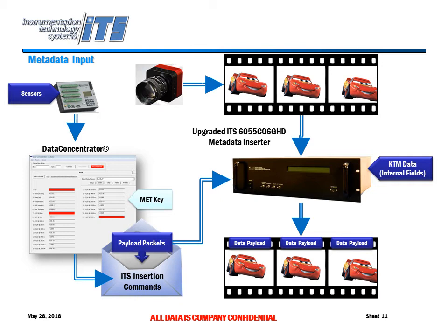This tool lets you define it yourself to say that this particular source, so many bytes in is this data, so many bytes in is this data, and as a result we parsed the incoming 30-byte record down to the bytes of interest, and then you can map those bytes as they come in to the fields you've defined with the key template.